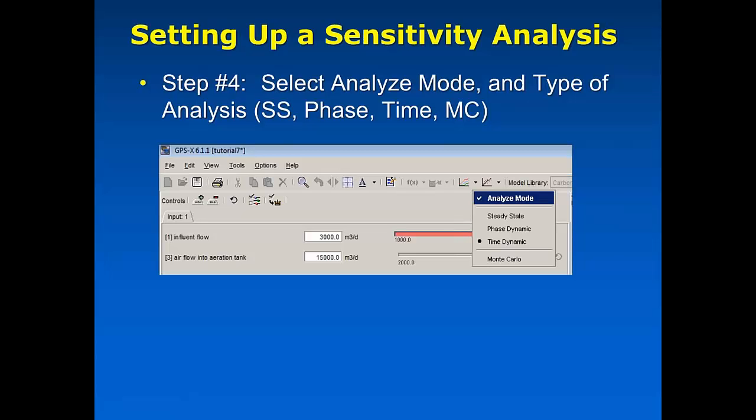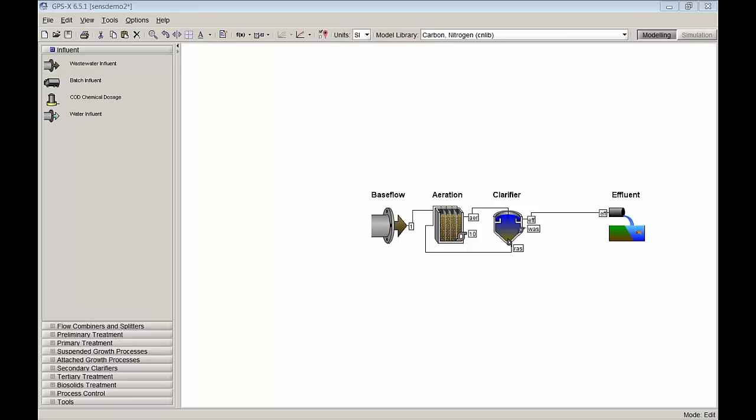So set the stop time. That's basically the same as you would do in any normal dynamic simulation. And then hit run, and then it'll start up the whole thing. And you'll notice that it runs one after another immediately. You don't have to do anything in terms of collecting the data. All of that will be collected for you and spit out for you in a report at the end. Okay, so let's take a look at what that would look like.